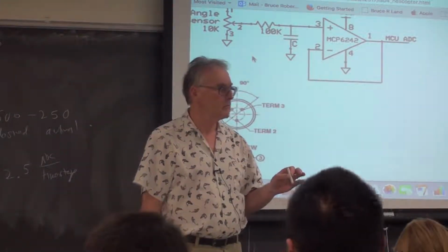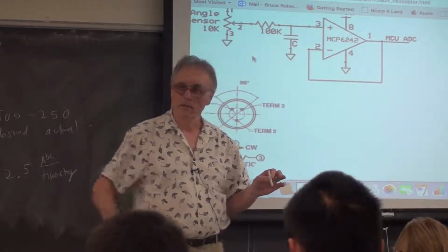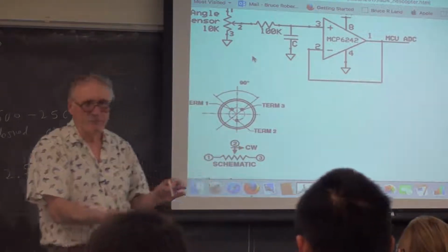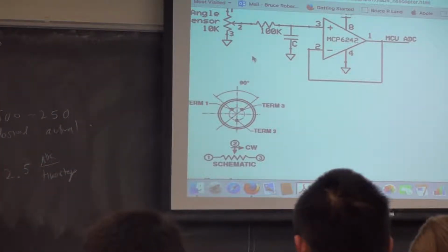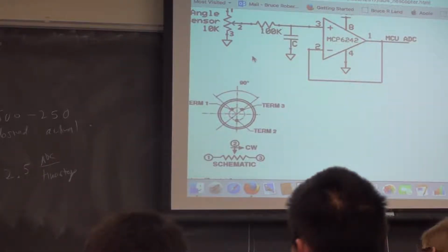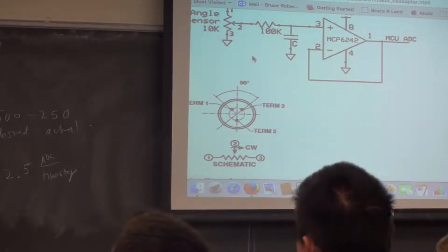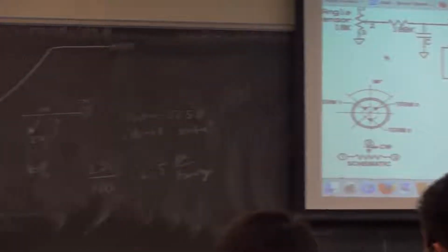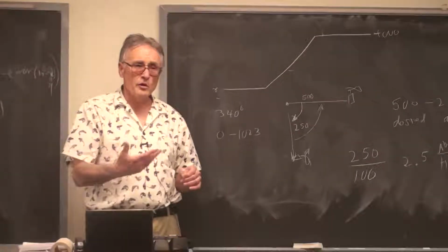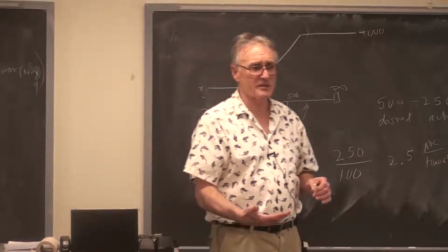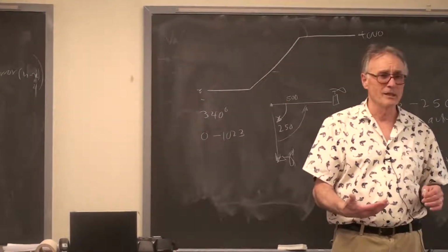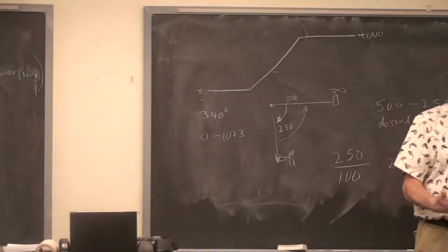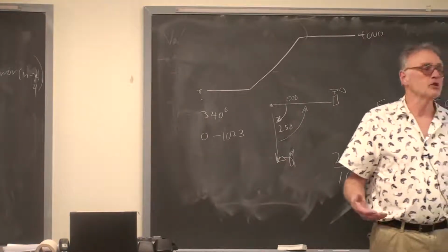Should you? Would that be a good idea? You don't want it running faster than the system's ability to respond to your new frequency. That's right. Therefore, since the bandwidth of the 4n35 is about 1 kilohertz, you can't go much faster. Also, a millisecond is rather short compared to the time constant of everything else. The motor has a time constant of 20 or 50 milliseconds. The pendulum has a time constant of half a second. Milliseconds should be fast enough.